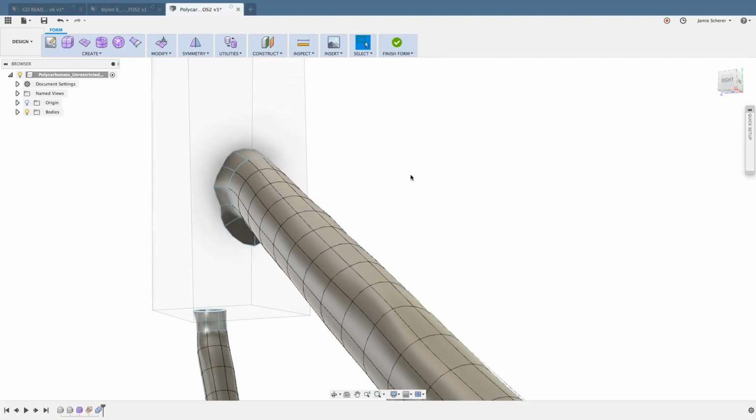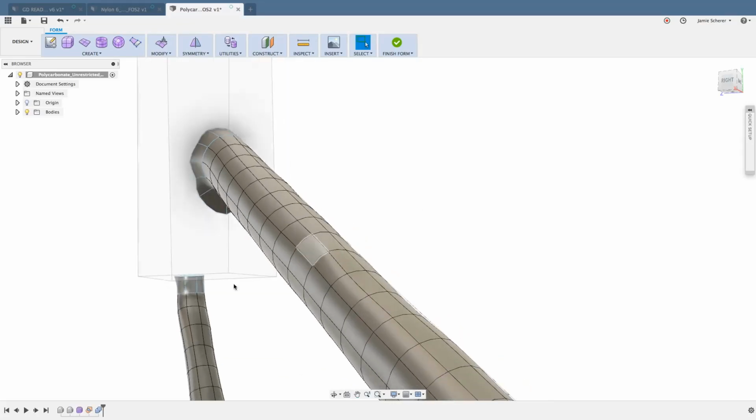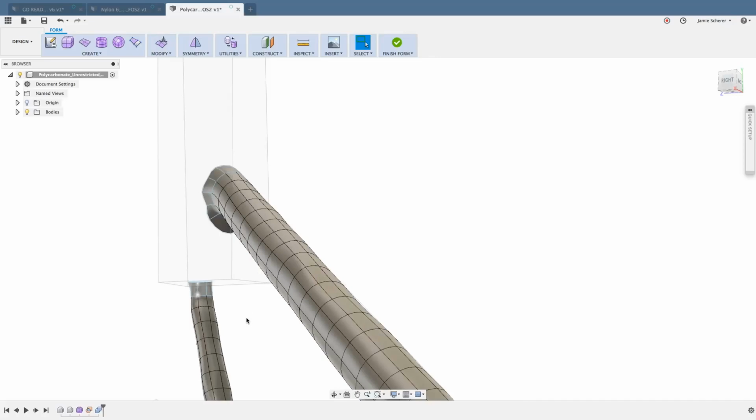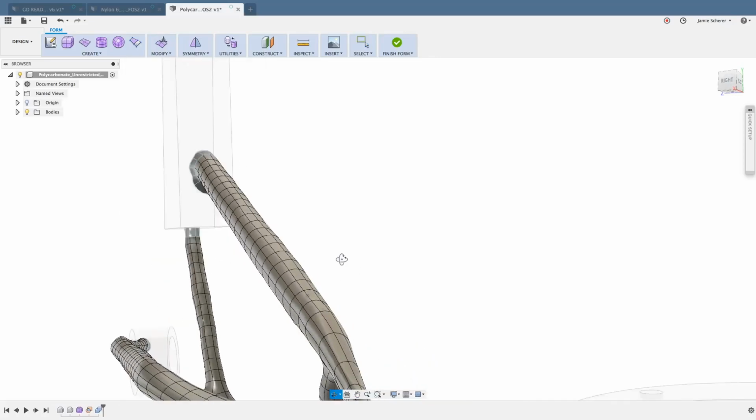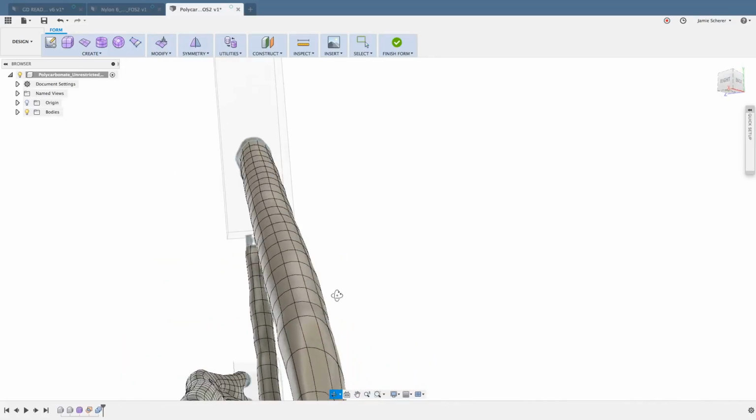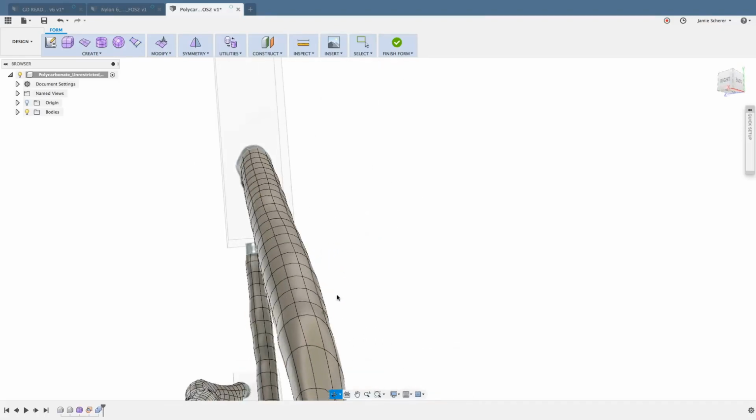And the reason it's doing that is because if we start to pull these edges off of the solid, then we'll have a hard time automatically turning this back into a solid when we're done. Now, we could unfreeze that. We might want to make changes or change that shape. Not a problem. We can unfreeze it later. But just know that anywhere the T-spline geometry touches up against a solid preserve, those edges are going to be frozen. The next thing that I'll talk about is some better ways to work with this geometry.